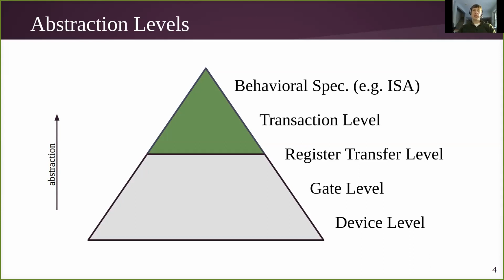This slide is depicting current design methodology, so a register transfer level design methodology, where the RTL model serves as our golden reference. For the most part, automated EDA tools take our design from RTL down to silicon. Transaction level design is elevating the abstraction level of our golden reference model, so the model that verification effort is targeted toward.